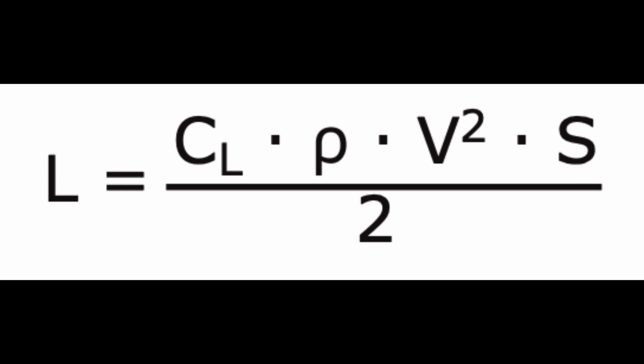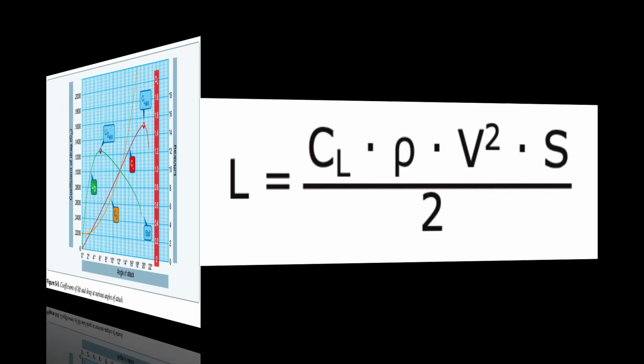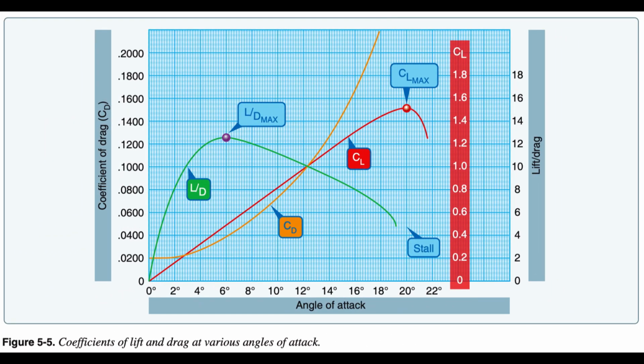Therefore, to keep the aircraft straight and level, not accelerating upward, and in a state of equilibrium, as velocity is increased, lift must be kept constant. This is normally accomplished by reducing the AOA by lowering the nose. Conversely, as the aircraft is slowed, the decreasing velocity requires increasing the AOA to maintain lift sufficient to maintain flight. There is, of course, a limit to how far the AOA can be increased if a stall is to be avoided. All other factors being constant, for every AOA there is a corresponding airspeed required to maintain altitude in steady, unaccelerated flight, true only if maintaining level flight.